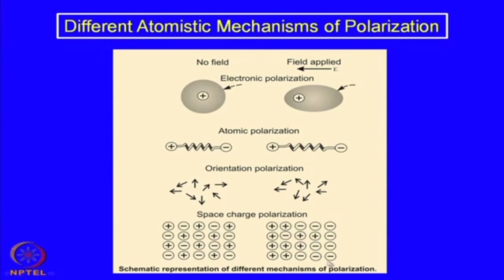But because of the short range movement, you can see here after the application of the electric field, the negative charges go towards the right and the positive charges tend to go towards the left. And because of the interface there, they are not getting fully neutralized with the electrodes placed here, and therefore more positive charge gets accumulated on this surface and more negative charges get accumulated on the other surface.